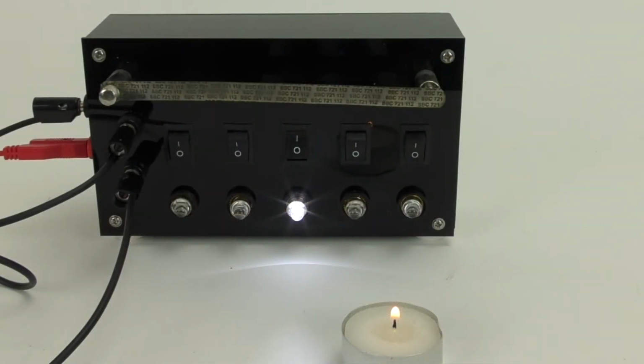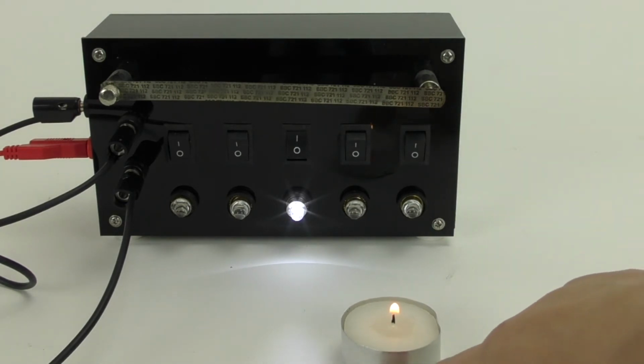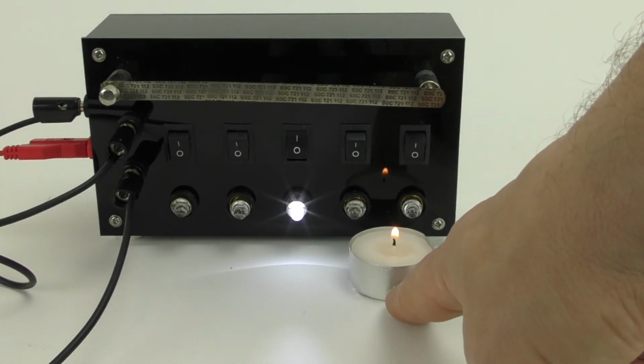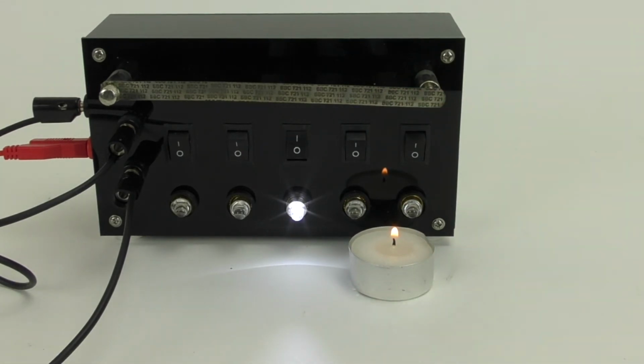We're going to use this one bulb as an analogy to being the circuit that's controlling your furnace. If you set the thermostat to a specific heat, the bimetallic bar has to bend away in order to break the circuit. So the furnace is going to keep going and going, and the candle will represent the ambient heat of the room. And when that ambient heat gets to your desired position, eventually that heat will cause the bimetallic bar to bend away and break the circuit.